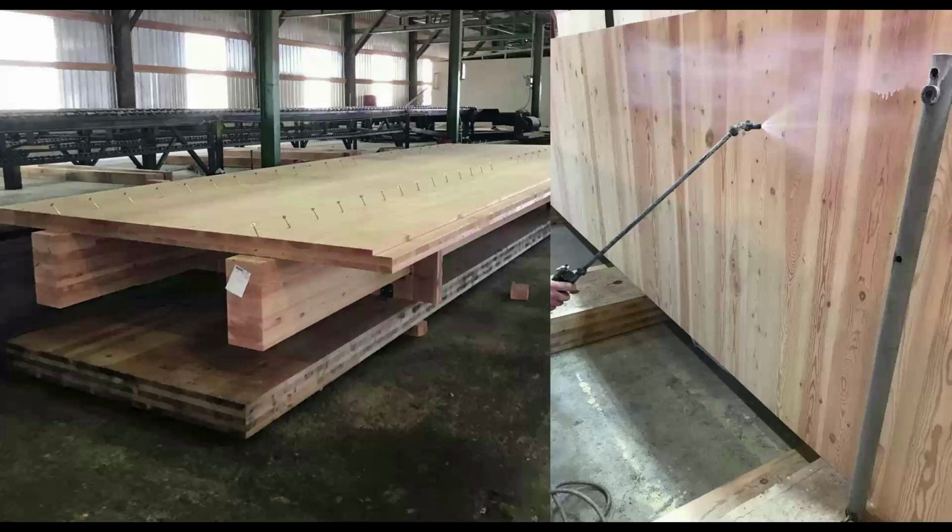Once the fabrication is complete, we can do additional items like assembly or sealer. The picture on the left is of a wood double T, and that's something that can be completed in the shop using 2 glulam beams with a CLT panel above, structural wood screws either perpendicular to the face of the panel or inclined. In the picture shown, you can see the inclined screws that had a standoff for a concrete topping slab. The picture on the right is simply a sealer being applied. That sealer will then be back brushed and give a good architectural finish to whatever the specifications of that particular project may be.